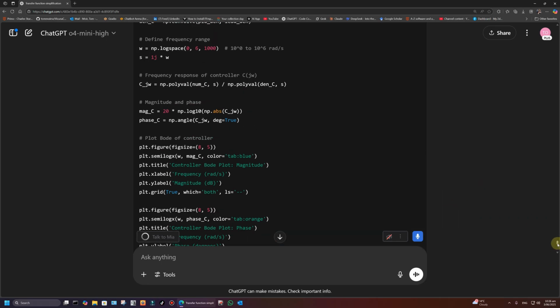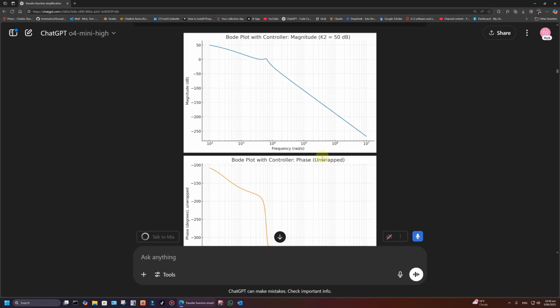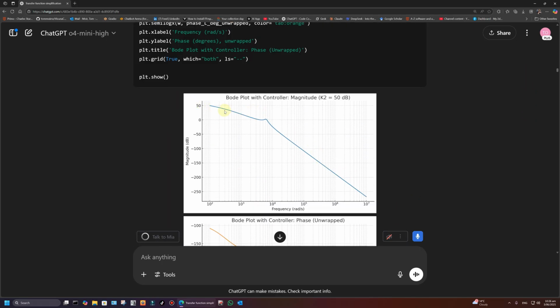So the original Bode plot will be minus 20 dB per decade, and that'll be minus 20 minus 40, which is minus 60 dB per decade. And if you don't believe me, you can work it out from the slope of the decade. You can say from a decade from 10 to the 5 to 10 to the 6. You can work it out from there.